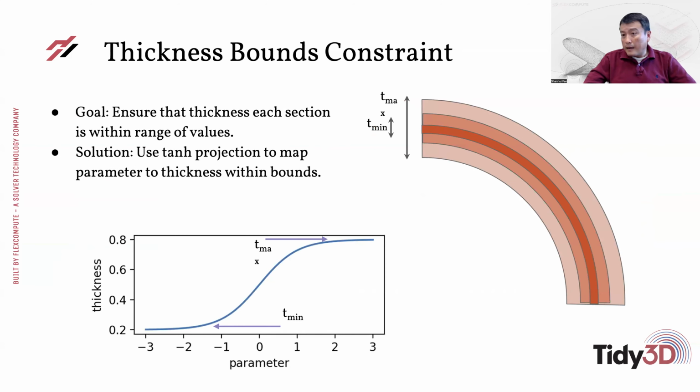So now, as usual, we would like to impose fabrication constraints associated with this geometry. One of them is that you can choose the inner and outer radius of this boundary so that it is not either too large or too small. And so you could constrain the waveguide bend region only in a certain region of the space. This can be done by using this hyperbolic tangent function to restrict where the inner and outer boundary is to a narrow value range. As we mentioned last time about the hyperbolic tangent function, this is a very useful function to impose a cutoff of a certain value, but in a smooth way so that you can take the derivative.